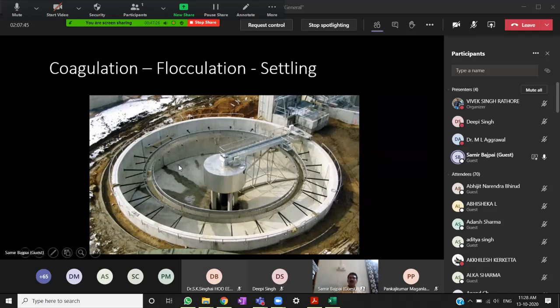Then it is released to the central column through this underground pipe, which is not as visible. This cover is there to reduce the velocity of the incoming flow. In this column, you have this paddle stirrer, and very slow mixing of the water takes place for flocculation. Here what we are doing is coagulation; rapid mixing is coagulation, so that the coagulant chemical is uniformly distributed and particles are destabilized.